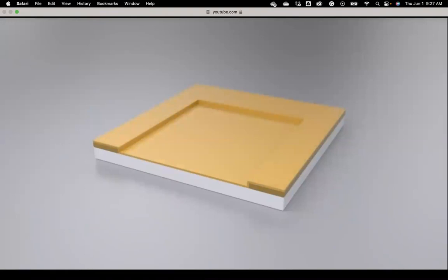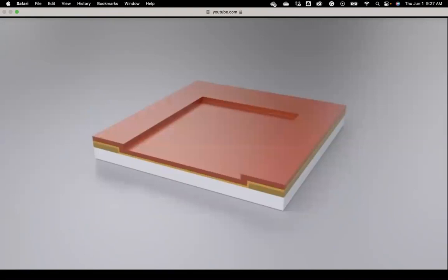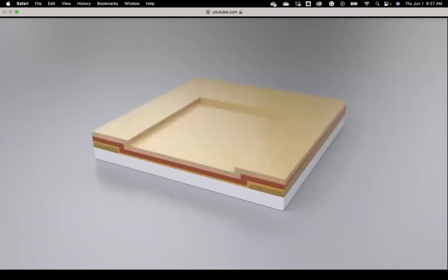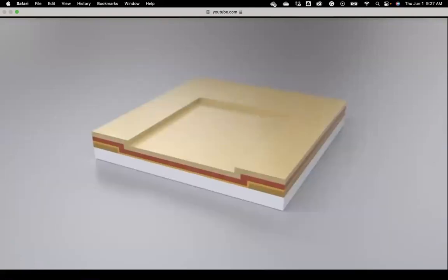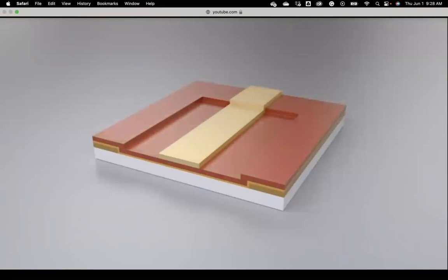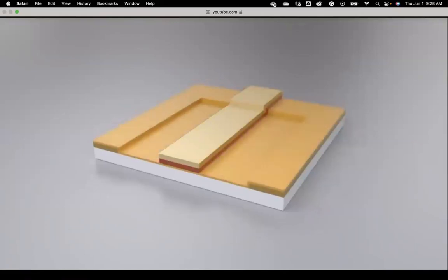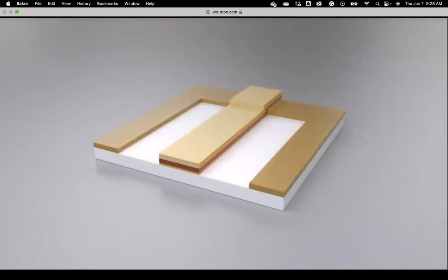Electrically conductive polysilicon is deposited on this insulation layer. Then photoresist is applied again, and the wafer is exposed to light through the mask. The exposed photoresist is stripped again. Now the polysilicon and the thin oxide layer are etched off. These two layers only remain intact in the center under the photoresist.